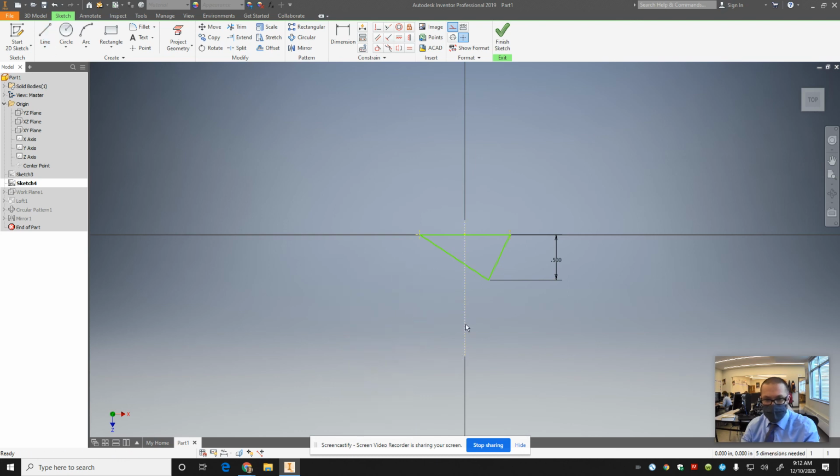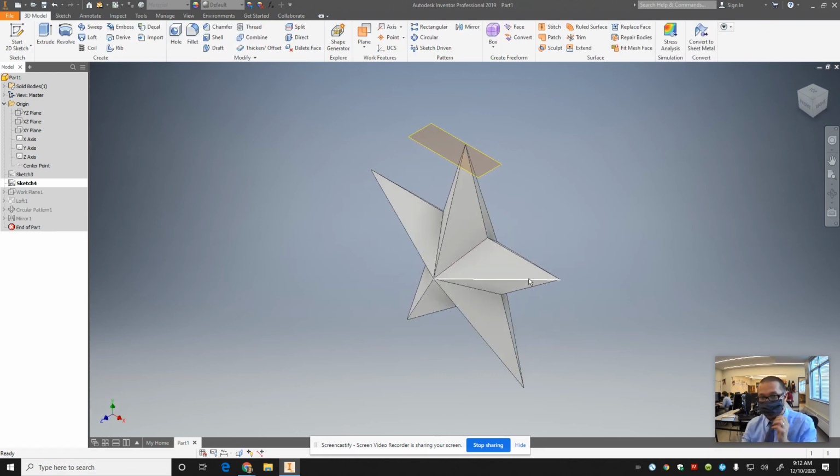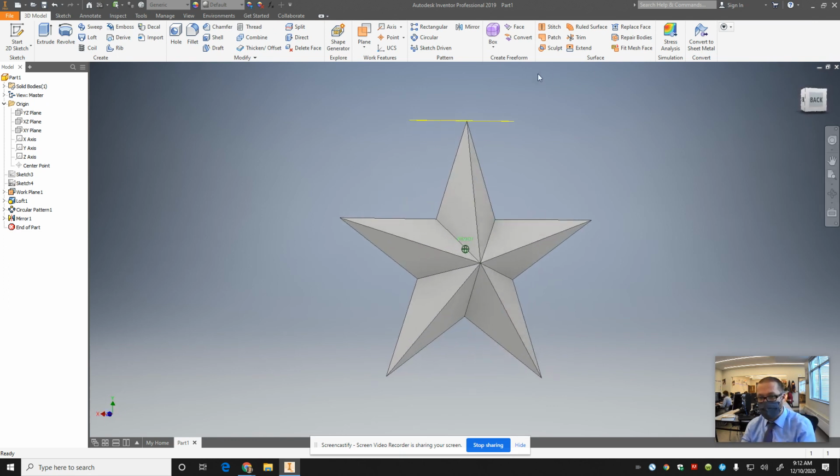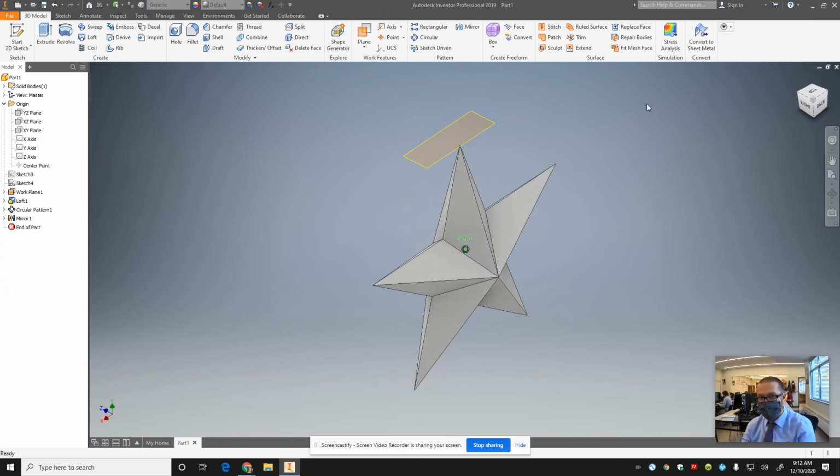All right. So that construction line, I'm going to lock it in place. So we learned about constraints before, and those are useful. Lock it in place, and then a coincident constraint of this point on this axis. Finish sketch. You'll make the whole thing a little wider if you want. And then from here, you could get pretty darn creative.